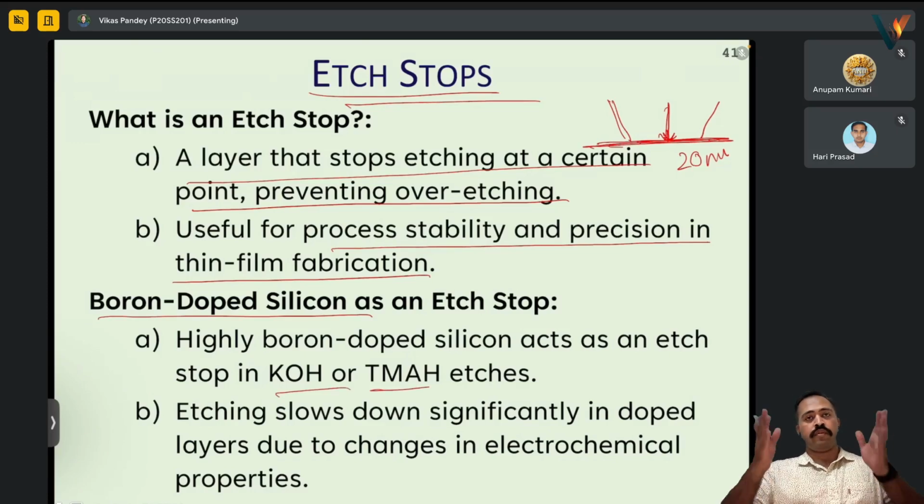So we know that a 54.7-degree angle has to be made. So if we want that at say 1 micron it has to stop, and then we have to broaden our shape or the structure we are making. We already know that using ion implantation we can do doping, and we can do doping at a certain depth also.